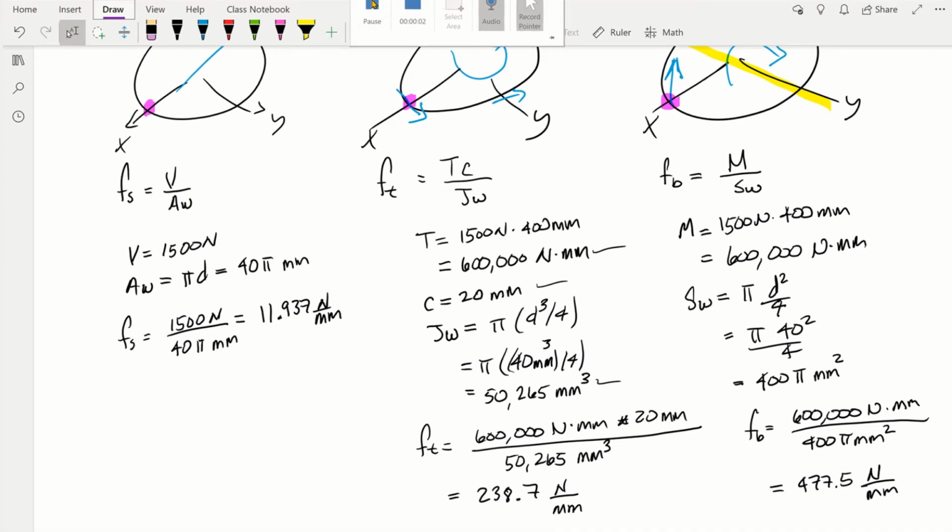We're almost done. We're in step 3. We determined the magnitude and direction of the force on the weld due to each type of loading. Next one, which is step 4, we have to calculate the resultant by combining the forces vectorially at the point where they're maximum on the weld. So we already said that our weld is circular. Here's our X and our Y axis. And this point over here, this is where the forces are maximum.